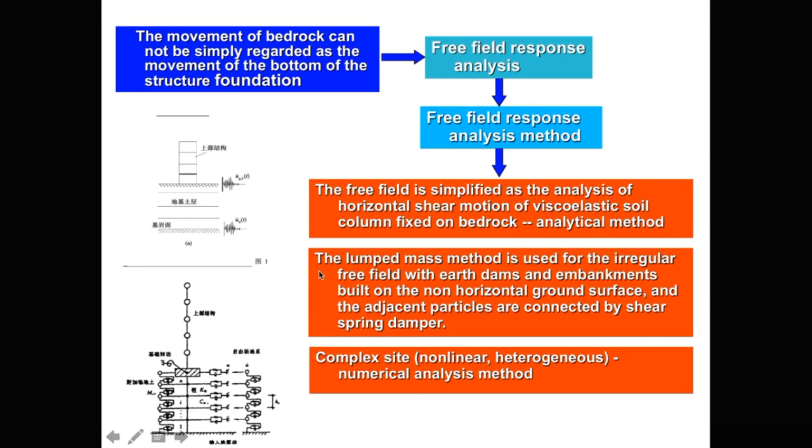And the lumped mass method is used for the irregular free field with earth dams and embankments built on a non-horizontal ground surface, and the adjacent particles are connected by the shear spring and damper.